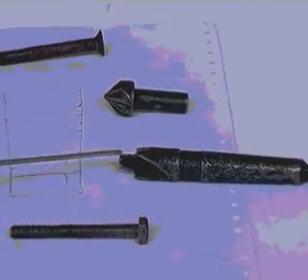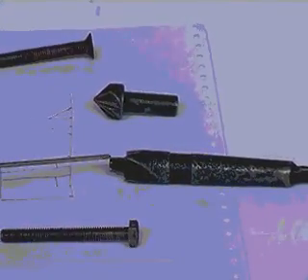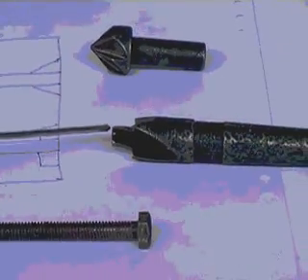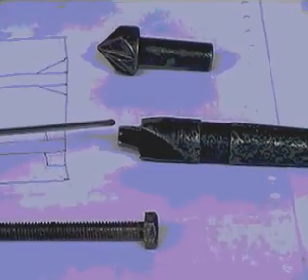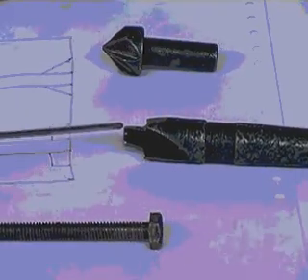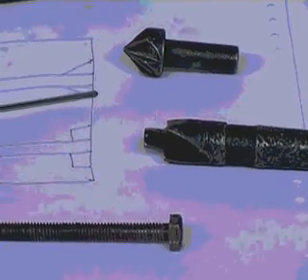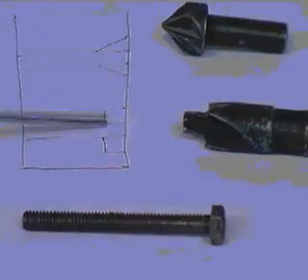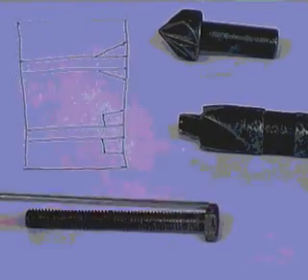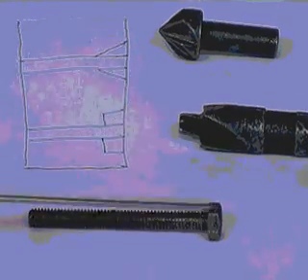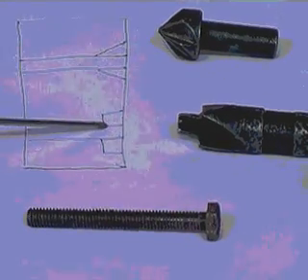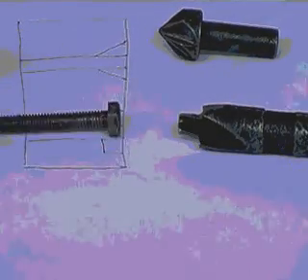This is called a pilot pin. It is adjustable and threaded. It can be made for various sizes. This pin does not allow the hole to be eccentric. It prevents the hole from getting eccentric. The hole is done exactly in the center because of this pin. We give this depth equal to the length of the head. So it goes inside the surface and its head is at the same level as the surface.